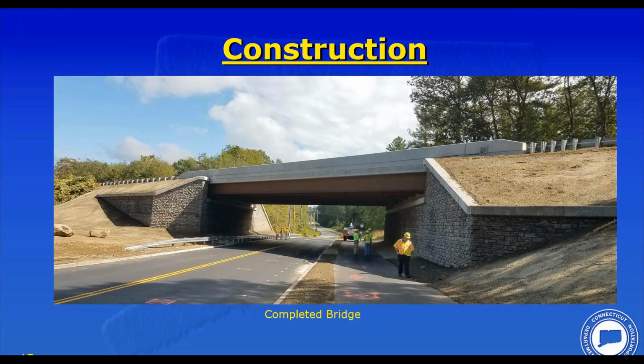Let's maybe, first of all, why was the ABC cost higher for this project when compared to the other example? Yeah, I think the key thing is the amount of time that we were saving. This particular project, with the fact that we could build the GRS IBS abutment underneath the existing bridge for both the ABC option and the non-ABC option, it took an awful lot of the construction off the critical path. And therefore, the time savings for ABC was only, I forget the number I had, it was a couple slides back, I think 5 months or 7 months.